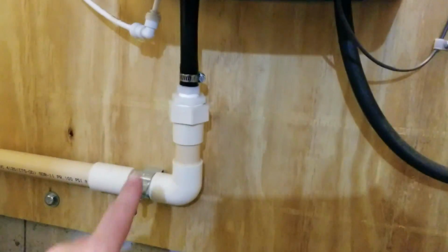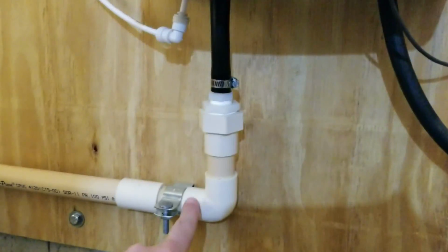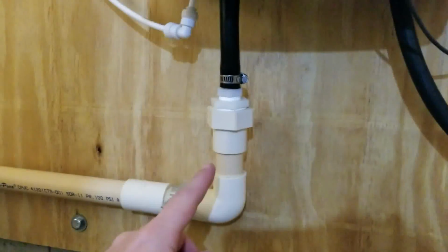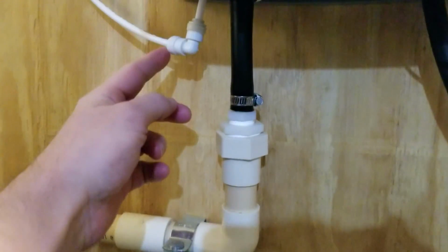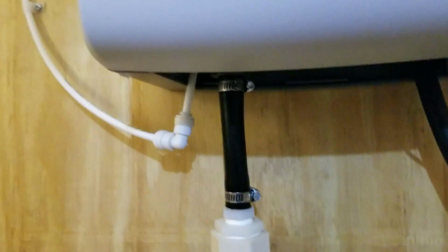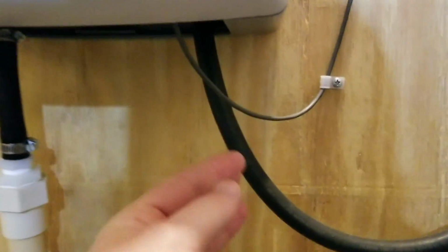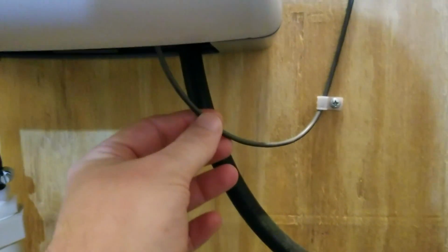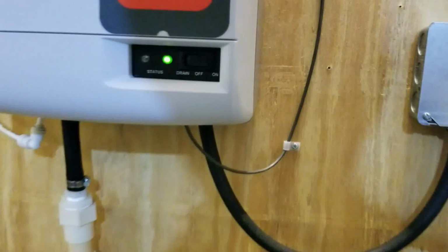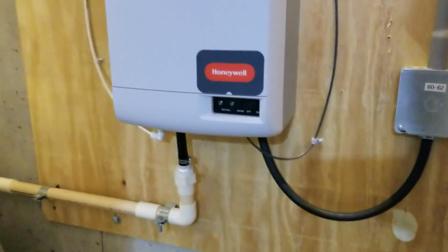Right down here, this is actually a drain. That's what you saw going over into the condensate pump. And then this is its city water supply line right here that I've got tapped into the city water line. And then this little thin wire here is the thermostat wire. This goes over there to that wiring center, and this is how the thermostat calls for humidity to be generated.